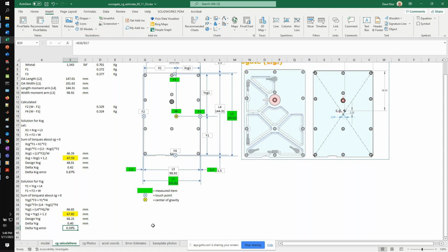Rotary is a kind of a vastly different thing. So the rotational inertia is going to be problematic because now you've introduced different rotational inertia about the CG because it's moved, and so that gets a little bit more difficult. There is a way to check the inertia, but we've got wires on this thing, and I had proposed using the string method for the period in order to determine the rotational inertia, and that would provide a torque equals I alpha calibration for rotation. So that's a way to do it.